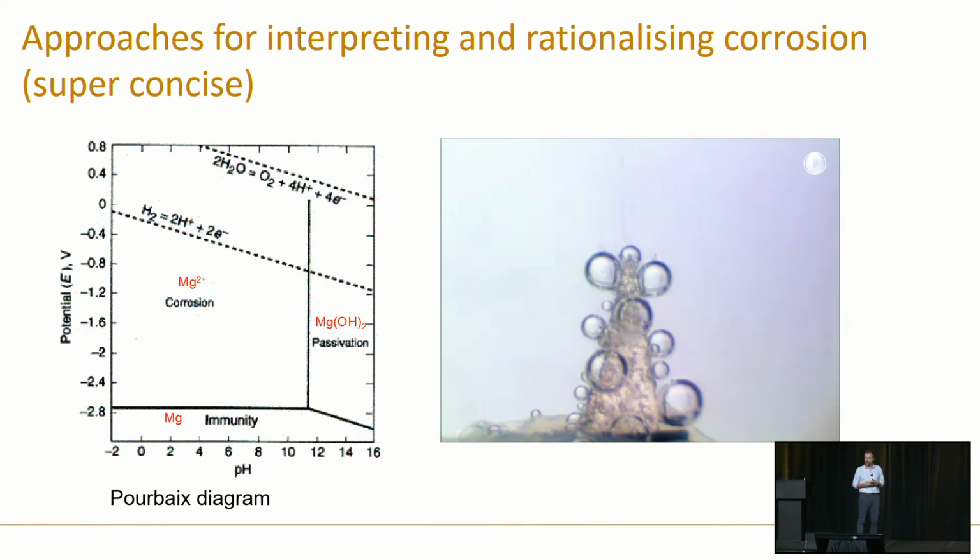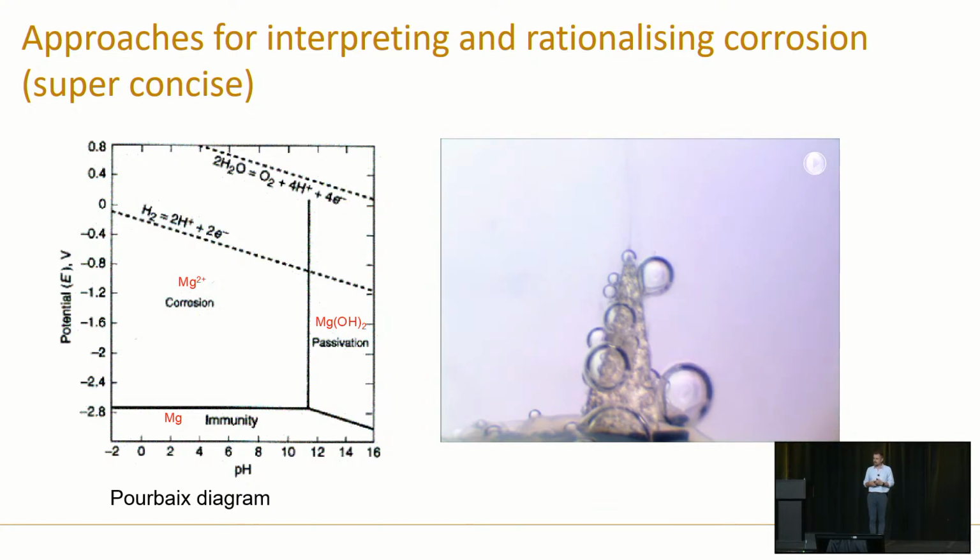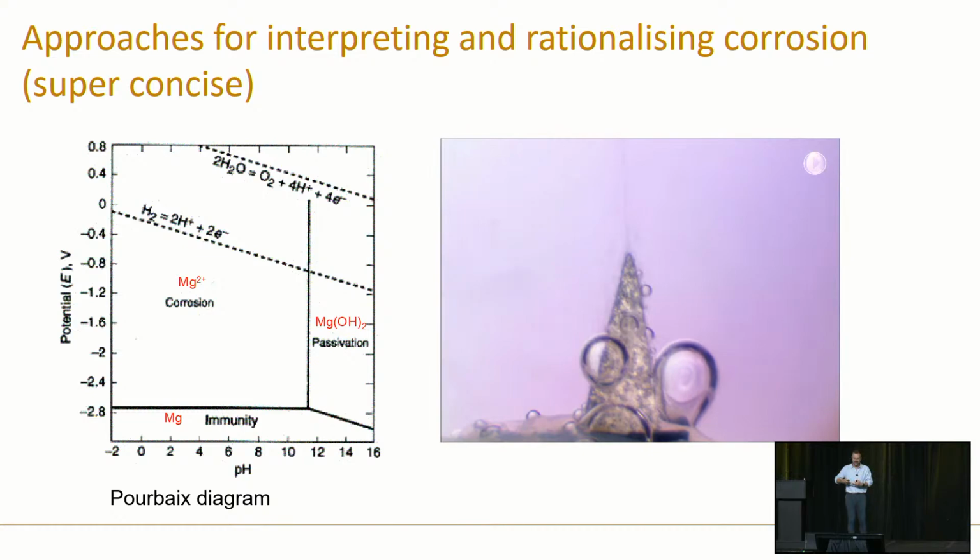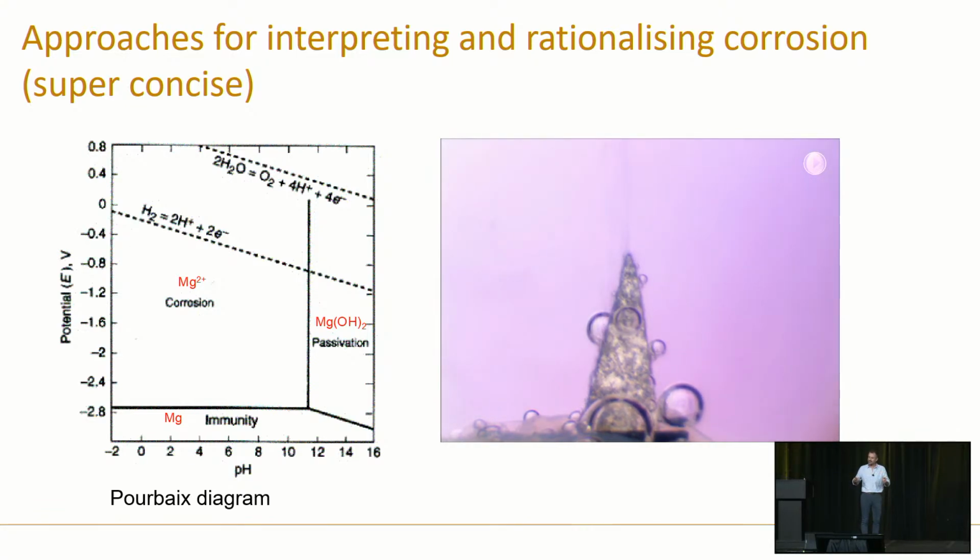Now, these are thermodynamic diagrams that really talk about the tendency for metals, and I call them inorganic, not because they don't have carbon in them, but because they're human-made materials. How do they behave? Pourbaix diagrams are really just a manifestation of the Nernst equation. You just put in the calculations, and chemists, electrochemists know that the Nernst equation works. And you can see across a range of pH and potentials, you get these different fields.